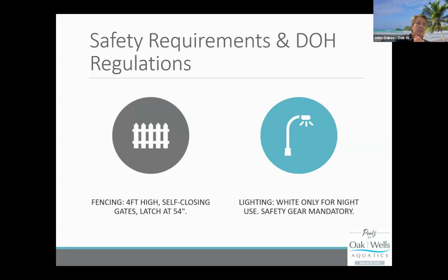Thirdly, the gates on any fence must swing out away from the swimming pool. The theory that the health department shares with us there is that if you have a toddler that comes up and leans on a gate that's not latched and the gate opens in, he can open the gate. And the skill set that's required to actually walk up to a gate that opens out away from the pool, grasp it, walk backwards and around it is greater than that of someone that could just lean on it. So they figured that that's a safer gate system than one that would swing in.